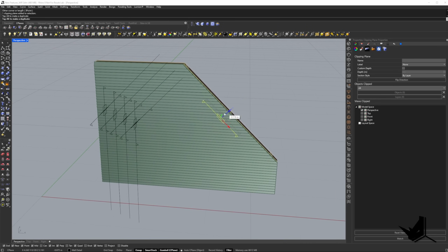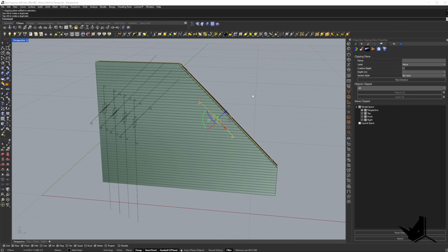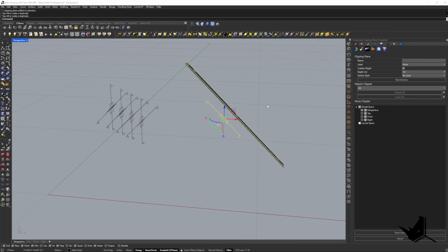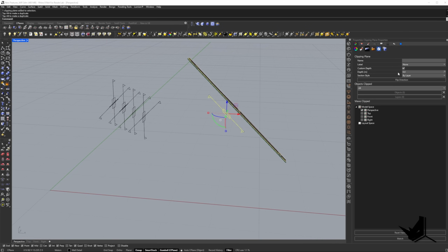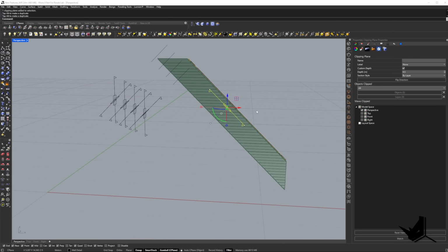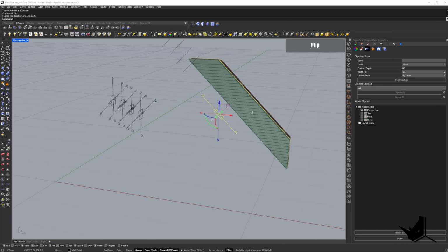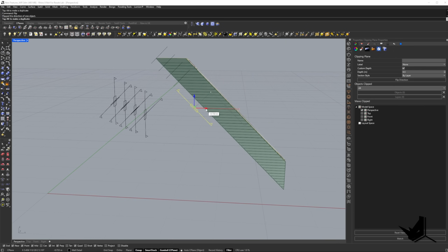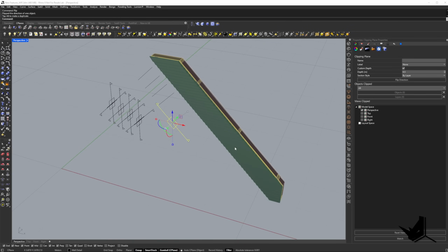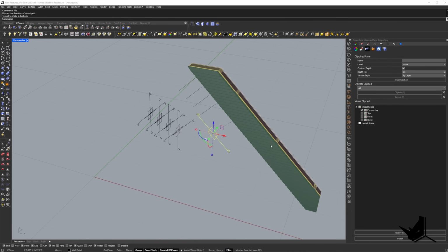And I wanted to show you what the depth does. If you go here and you go custom depth, and here you can control the depth in meters. Let's say 0.5. And you can see here with 0.5 how I'm able to cut only that part. Okay, I can use flip command if you want to flip on the other side. And by moving this plane, you can see here how I'm only selecting that individual part of my wall, and I can do this many different times in many different areas.